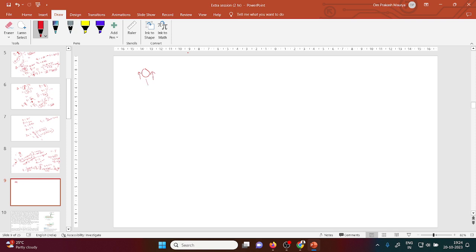See, this is the buoyant force, this is your FB, and this is your drag force, and this one is the body weight. So the weight of the drop is how much? Weight of the drop is rho of water, G, into volume.